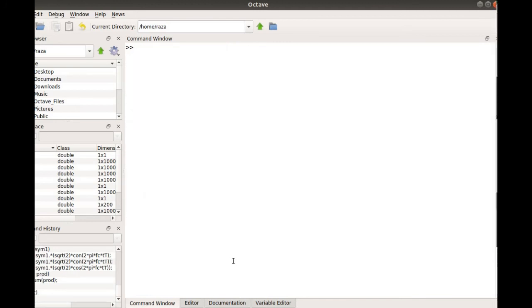In the second branch, let me give it a name, product 1. Product 1 is the signal, which is symbol 1, multiplied with our carrier, which is minus square root of 2 times sine of 2 pi f c t, and our T is just one symbol.